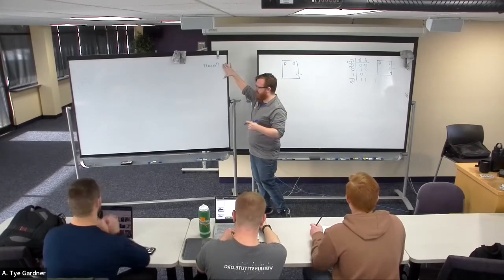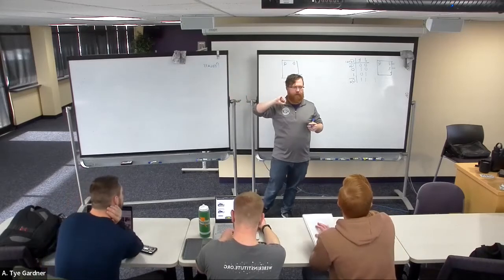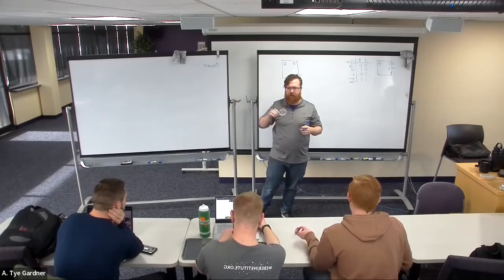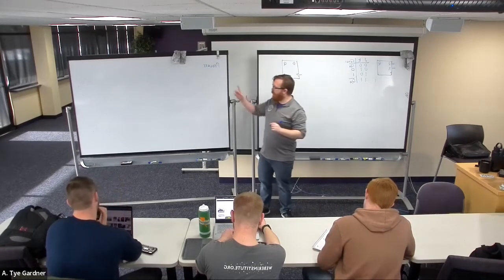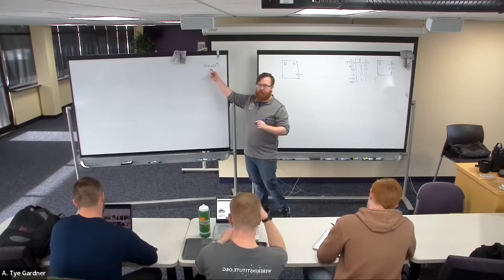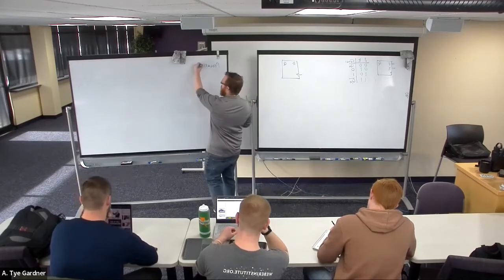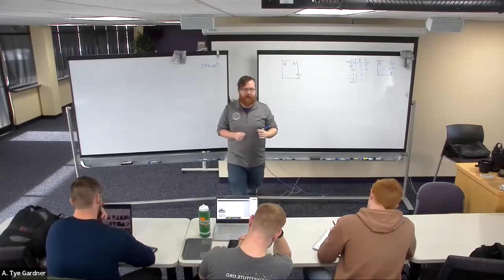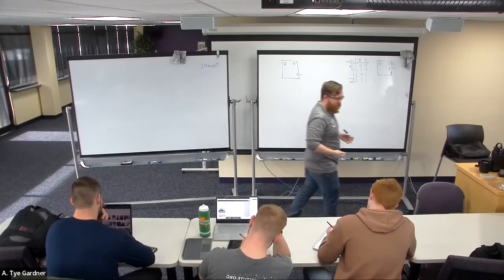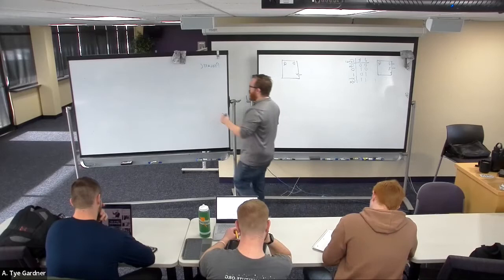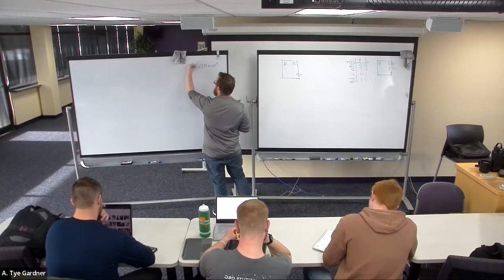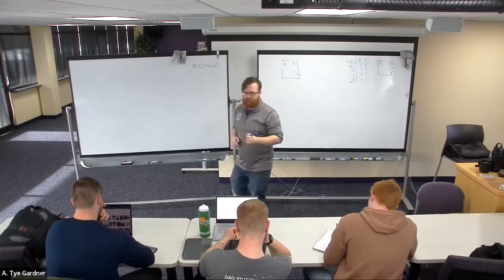So let's look at the process. A process means that it's now sequential logic. One thing happens and then the next thing happens. In the test bench, we never had to worry about what we call the sensitivity list. But once we're trying to design logic, I need to tell it, what do I care about? When should this process run? And if I'm designing a clocked circuit, it's always going to care about the clock.